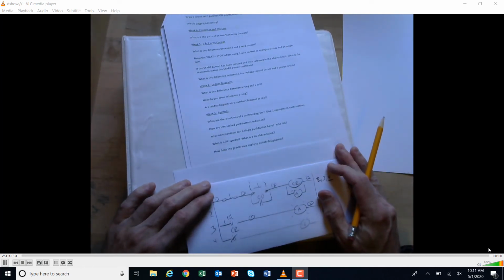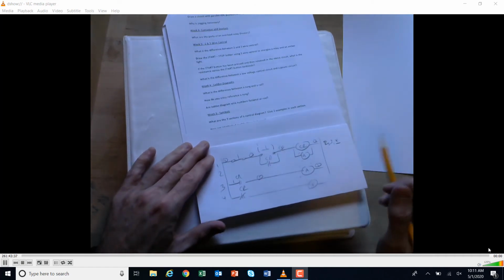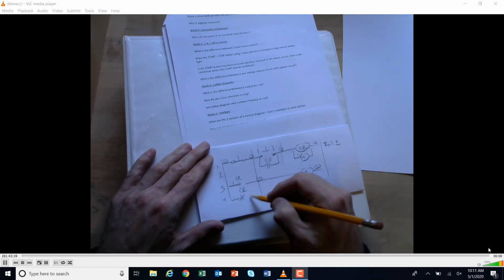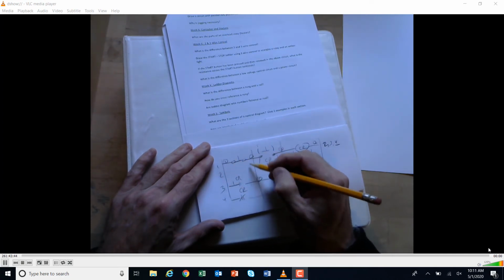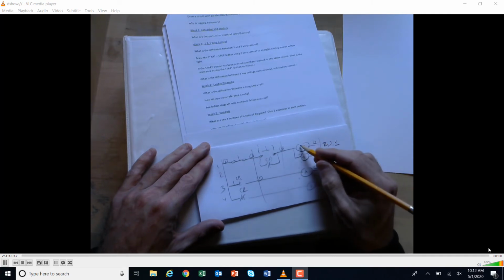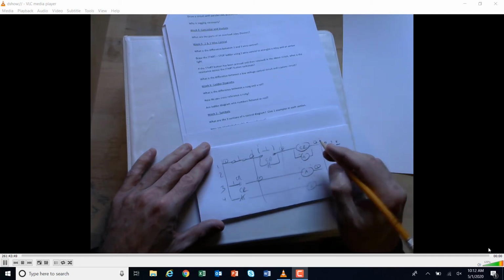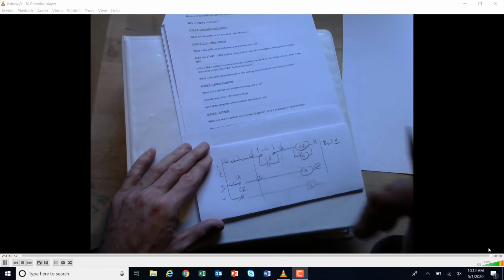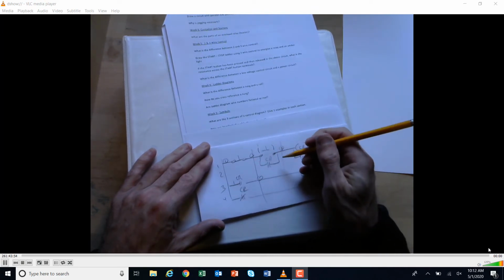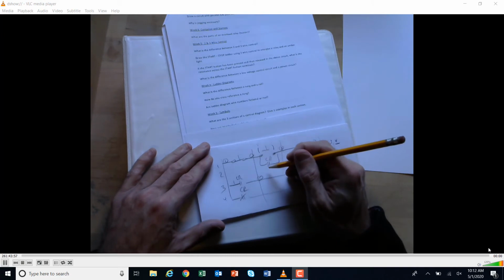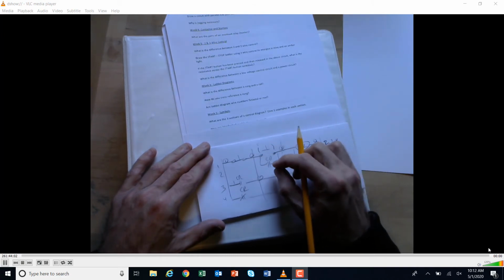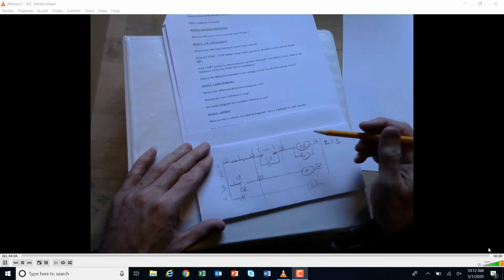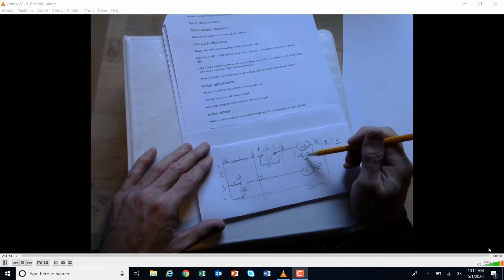Symbols. What are the three sections of a control diagram? So what we had on the control diagram, on the left, a lot of times you have your inputs, and on the right, a lot of times you have your outputs, your field devices. And then in the middle, typically, but it could be a little bit different, is the logic commands, where your control relay contacts or your timed relay contacts might be situated, but not always. But the loads, you're always going to find the loads or the output devices here on the right, okay?